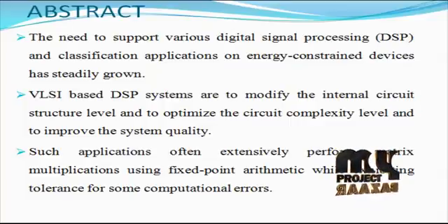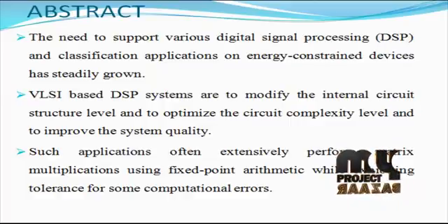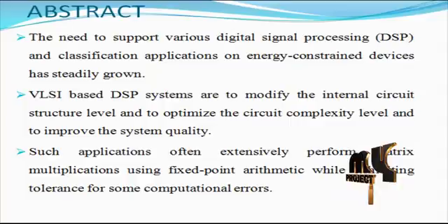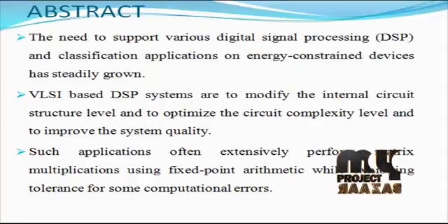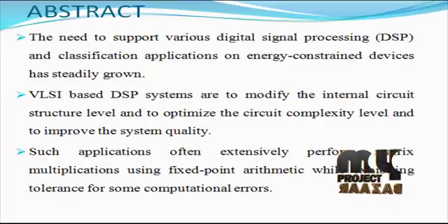In this brief, we propose an approximate multiplication technique that takes m consecutive bits for each n bit operand, where m is greater than or equal to n by 2. An m bit segment can start only from 2 or 3 fixed bit positions, depending on whether the leading 1 bit is located in a positive number. This approach can provide much higher accuracy than simply truncating the LSBs, and it identifies the overall approximate architecture for built-in DSP based systems.